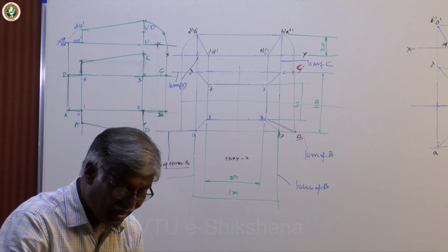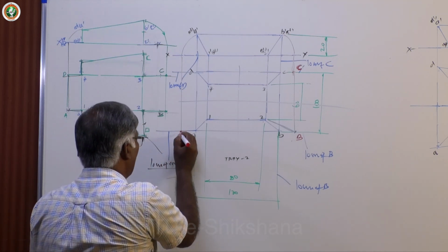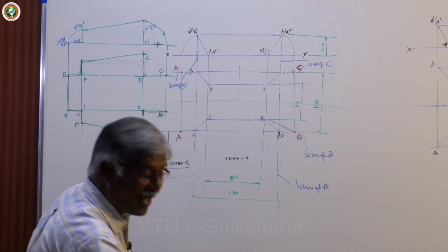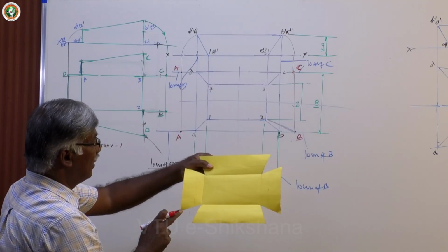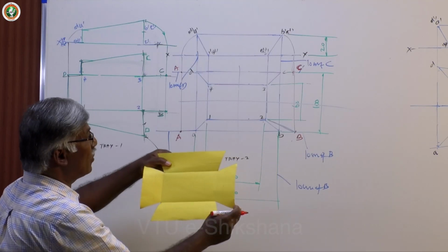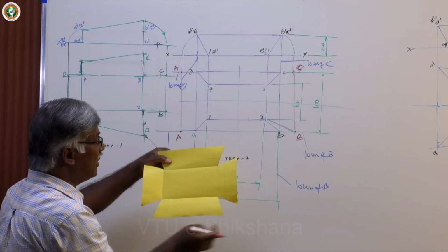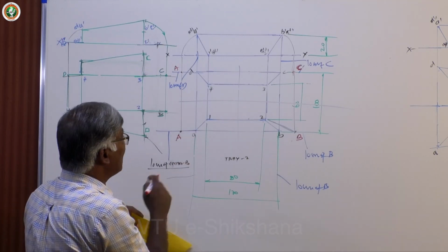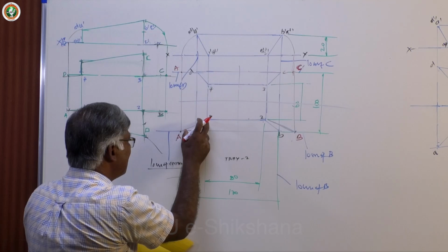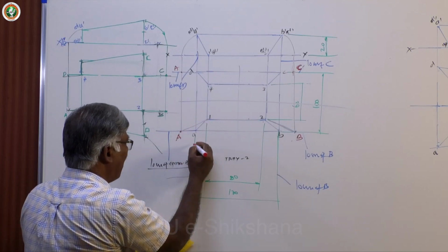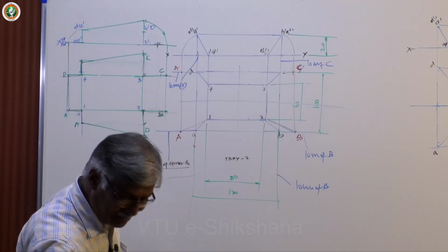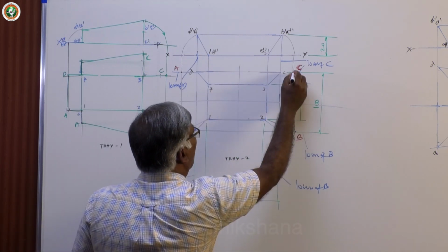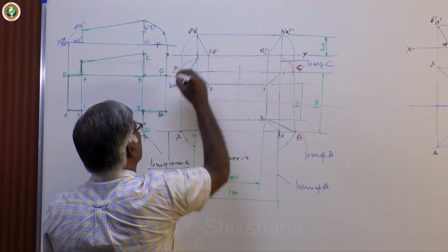Okay. Now, I can just say this is A, capital A. This is again A. That is with respect to 1, 4. So, I have identified A and D. And also I identified B and C. Now, how to identify these two? Again, we have the same locus. See, through A, you have already drawn the locus. Take this as the distance reference, take this equal to the radius, draw an arc on this. So, you will get, see, I will show the arc reference. Same, all throughout, draw arcs on the respective loci.